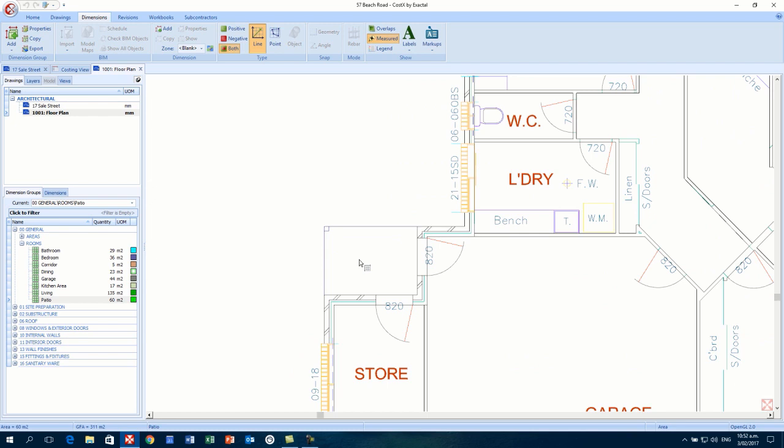So regular shapes being squares, rectangles, or triangles. We can pick up the area of regular shapes really quickly by holding down the Shift key. When I hold down the Shift key on the keyboard, you'll notice that there are 4 crosshairs that are sent up from the mouse cursor. Wherever these crosshairs meet a line, it will want to enclose that area.